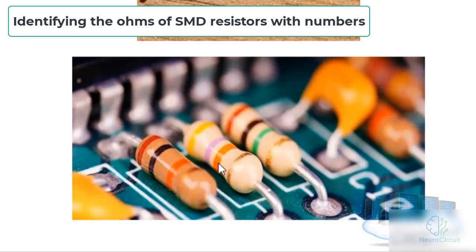So they won't have any visible differences from each other. This is one of the techniques you need to use in repairs. So if you see, for example, there are 3 resistors and 2 of them are the same color, but the other one has a different body color and it looks baked like this, which is quite obvious. It means it's been exposed to a lot of heat and might be damaged, so it's better to replace it.